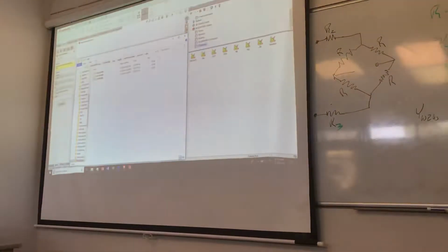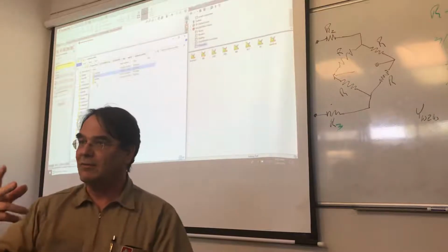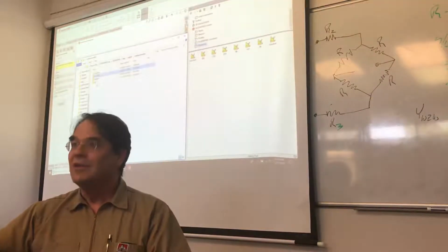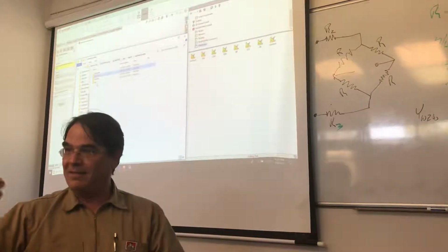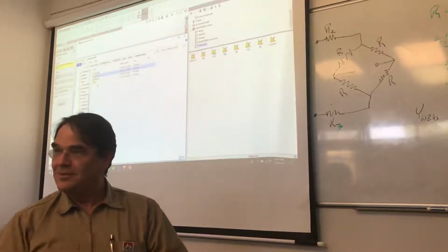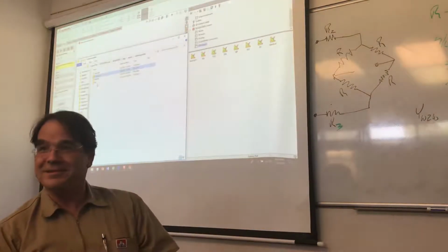Well, what we want to do is save our ANSI 2 thing, which is this one here. This one wants to get saved to this directory: SolidWorks Corp, SolidWorks Lang, English, Weldment Profiles, and whatever name we have. I've got 4 names here, right? There were only 2 originally: ANSI Inch and ISO. And so I have added the ANSI Inch 2 one and the custom one, which might be an indication of what the second part of the assignment is.